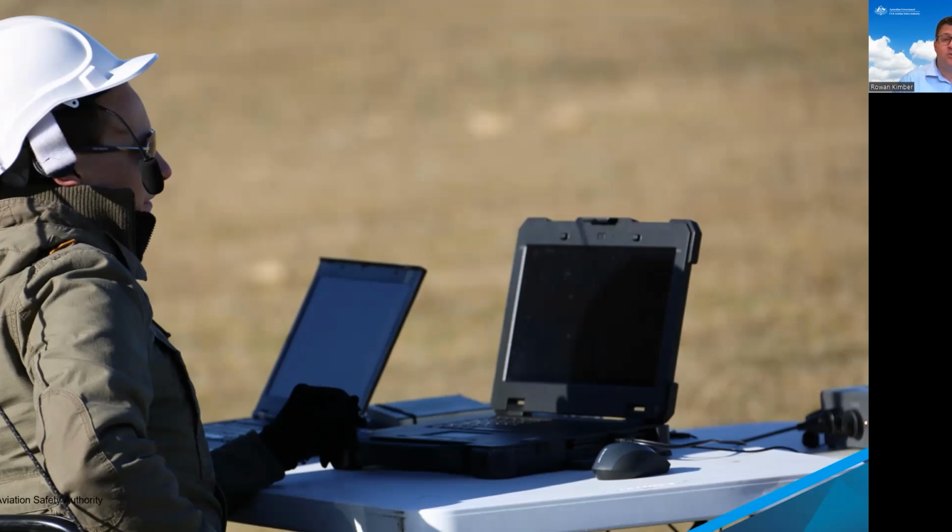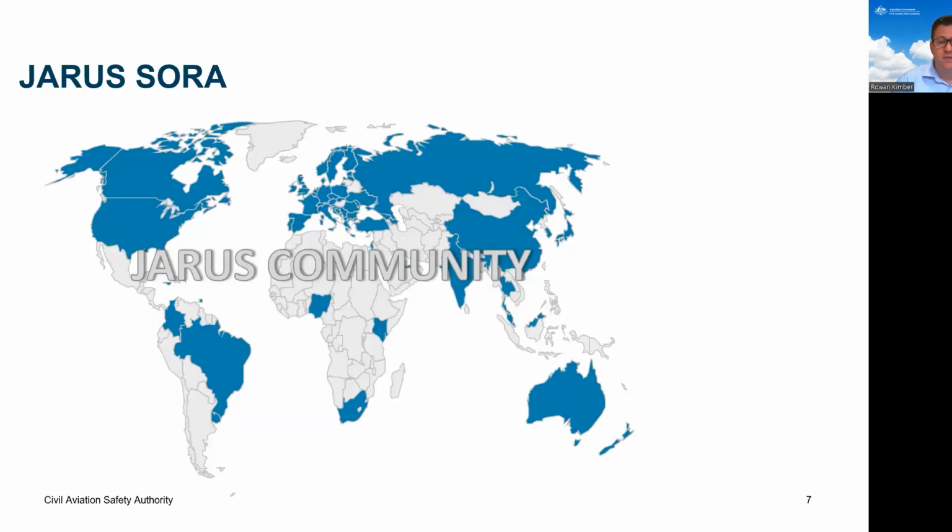And for Australia, this is where SORA now comes in. Today, SORA is the preferred methodology chosen by CASA for the assessment of most BVLOS concept of operations. And I say most, there are some fringe cases that sit outside of it. Unlike some nations, CASA has not enshrined SORA into our regulations. In theory, an operator can choose to use any risk methodology to determine that their operations are safe. In practice, though, the use of SORA streamlines the assessment process and provides a common language between the regulator and the operator, such that now it's often the most sensible option.